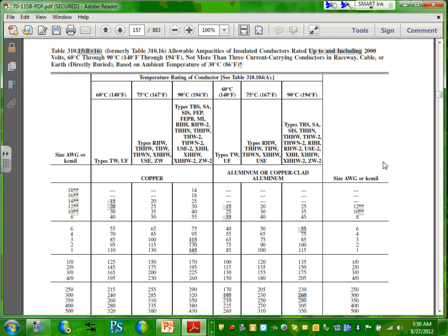I want you first to put a divider right here, and box these areas here. I always box them. Conductors up to number 1. Up to size 1. Unless you know otherwise. Conductor up to number 1, you default to the 60-degree column.